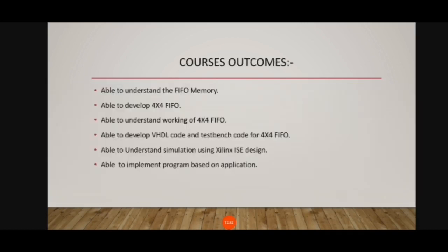Course outcome. By developing this type of application, we are able to understand the FIFO memory and develop 4:4 FIFO. Also, the working of 4:4 FIFO we have understood. We have developed a VHDL code and test bench code for 4:4 FIFO. Also, we have understood simulation using Xilinx ISE design and are able to implement programs based on applications.